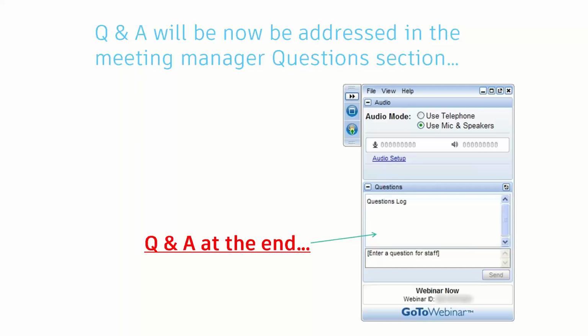I don't know of any software out there that'll actually do that accurately. But depending on the situation, you could manipulate the file to where we could get it to flatten with sheet metal. There's no guarantee it'll work because you get into things like lofted faces. If the material is not a uniform thickness, that's a big killer right there. Sheet metal will not flatten a non-uniform thickness model. Everything has to be uniformly thick. So if that's coming into play here, no, it's immediately out of the question. But if it's a uniform thickness and depending on the geometry, it's possible, not always.